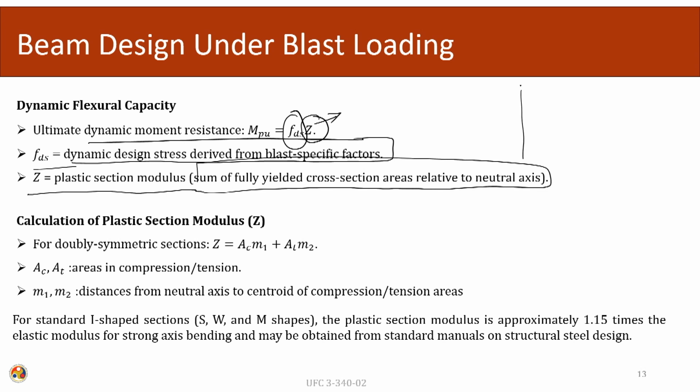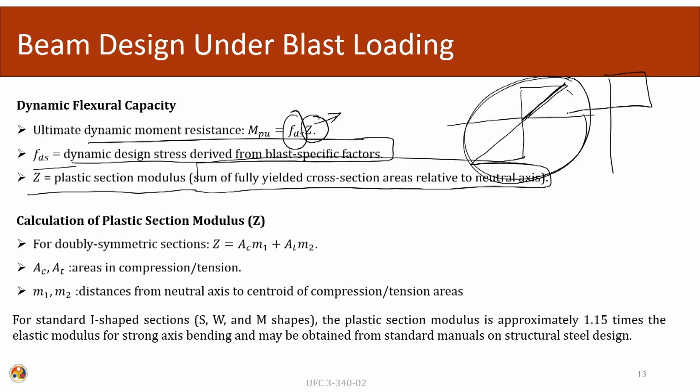In the elastic design, we were used to calculating the section modulus with the system remaining in the elastic state. Here we will use a design modulus where my entire section is in the plastic range. This is called the plastic section modulus, and the earlier one, the S that we were used to, was the elastic section modulus. The calculation of the plastic section modulus.